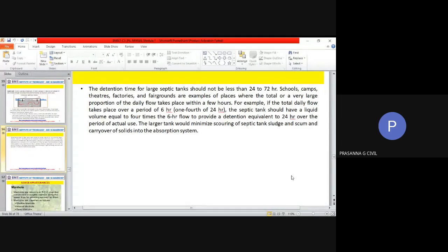Their maintenance is also relatively easy. Only periodically you will be clearing out the sludge either from the pond or from the septic tank. Hence, called by the name low cost treatment. You have oxidation ponds where you have very large land area to be utilized, whereas the septic tank is an underground tank. So these are the systems available for you for low cost treatment. With that, the low-cost treatment portion is over.